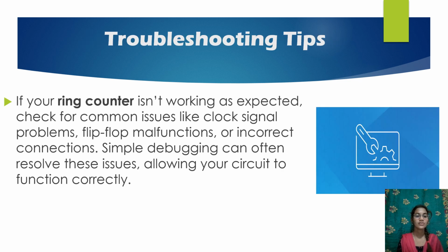Troubleshooting steps. If your ring counter is not working as expected, check for common issues like clock signal problems, flip-flop malfunctions, or incorrect connections. Simple debugging can often resolve these issues, allowing your circuit to function correctly.